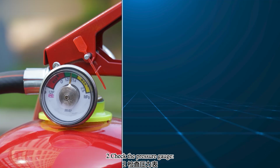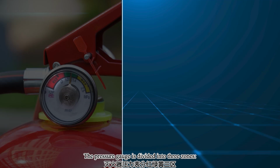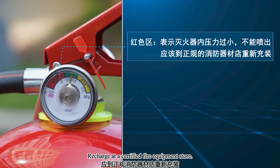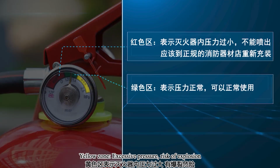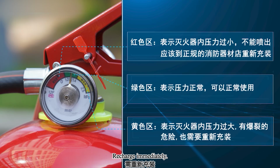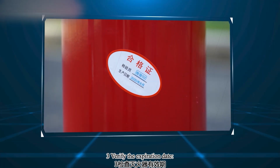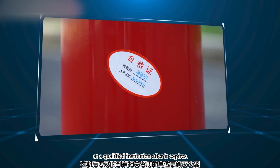Second, check the pressure gauge. The pressure gauge is divided into 3 zones. Red zone, low pressure, unable to discharge. Recharge at a certified fire equipment store. Green zone, normal pressure, safe for use. Yellow zone, excessive pressure, risk of explosion. Recharge immediately. Third, verify the expiration date. Replace the fire extinguisher promptly at a qualified institution after it expires.